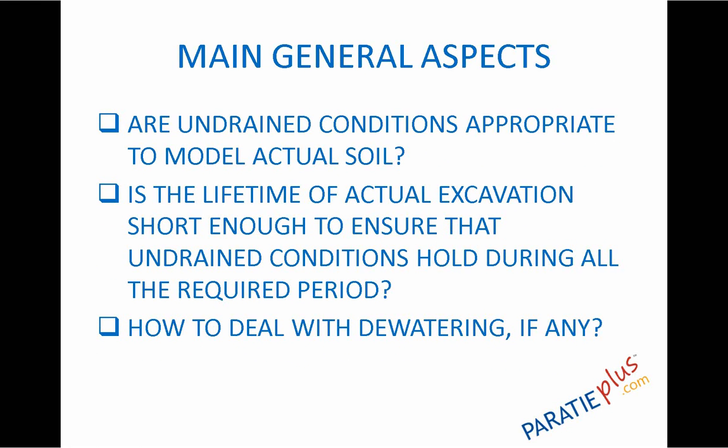What a designer has to ask himself is whether undrained conditions are appropriate for his soil for that problem, and if the lifetime of the structure or the retaining wall is sufficiently short to ensure that such undrained condition holds during all the required period.